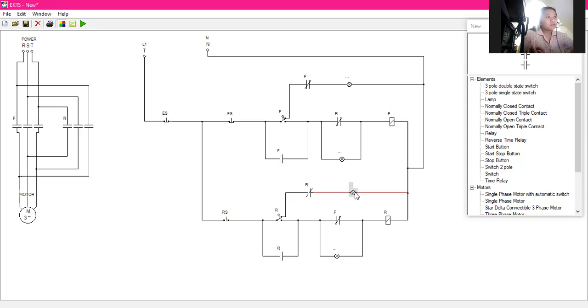So we can say this color will be red, and this color will be green, and this color will be blue. So if we run it, when we turn on the breaker, the red lights will turn on. So we have current flowing, but our motor is not yet functioning. But it is an indicator that our motor is okay.